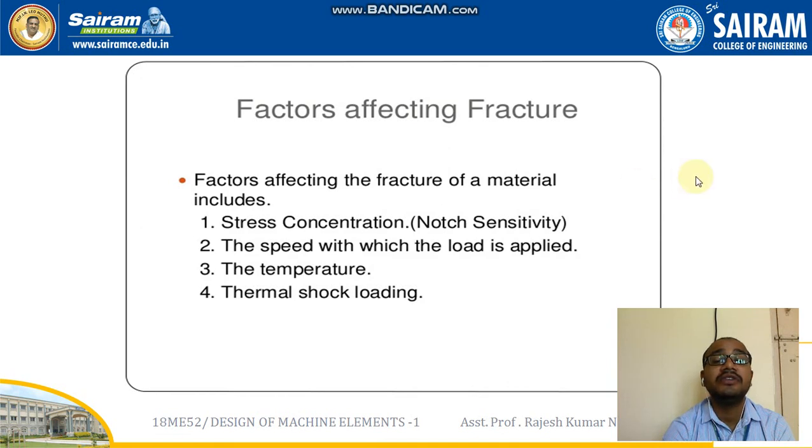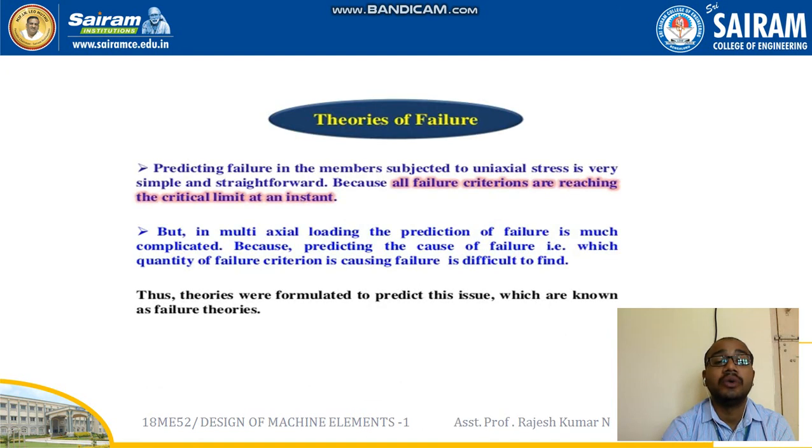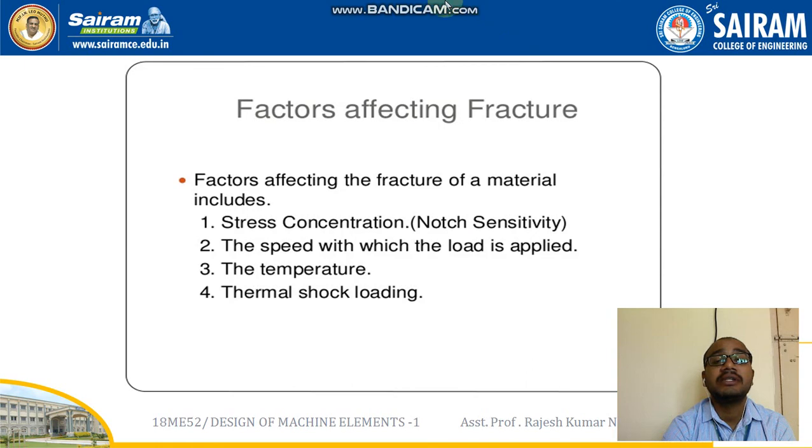The factors which really affect the fracture are stress concentration, where the notch sensitivity, this topic we will be discussing in detail, then the speed with which the load is applied, the temperature, and the thermal shock loading. So with this the video gets completed.